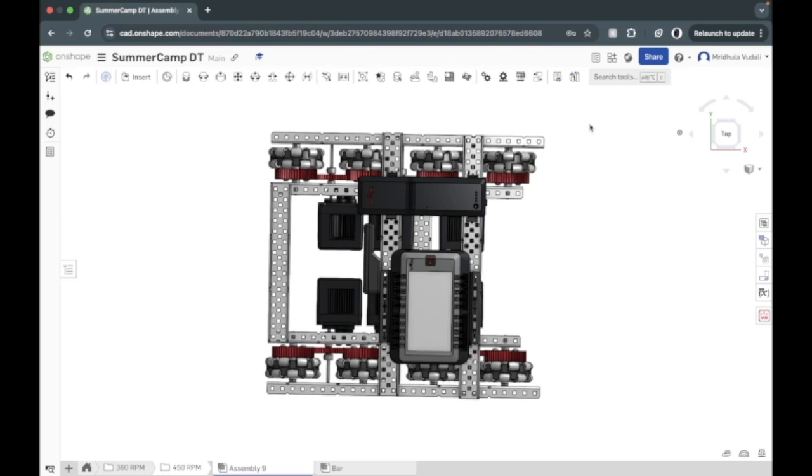However, once you start adding more assemblies to your drivetrain, the positioning of your radio becomes a bit more complicated. According to the VEX library, here are some of the best practices when it comes to your radio. The higher the mount location on the build, the better. Do not mount the V5 robot radio in a steel box, meaning do not surround it with metal. Keep the thinner part of the V5 robot radio away from the other metal. If you don't follow these suggestions, you run the risk of the radio disconnecting.